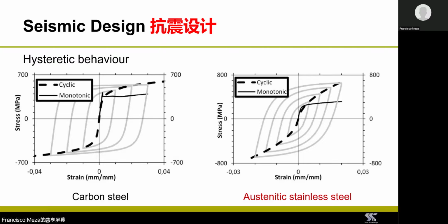When carbon steel is cyclically loaded beyond its yield strength, its strength increases with each cycle, but after a few cycles, it stabilizes. Now, for austenitic stainless steel, this doesn't occur, and their strength continues to increase with each cycle, which is why you end up having a larger cyclic hardening than for carbon steel. For duplex stainless steel, the behavior is something in between that of carbon steel and austenitic stainless steel. Being able to predict this cyclic hardening behavior is also very important when doing capacity-based design.